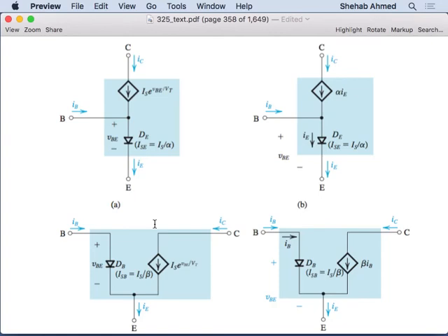The gain is different. You remember in the MOSFET, in the active region, what was the drain current controlled by? The overdrive voltage squared, in the saturation. Here, this is also relevant in the active region, because this is forward only in the active region, and I've created the other one reverse. That's why all the equations apply to what we're talking about, active and reverse, right? Active in the emitter base junction and reverse in the collector base junction here. So I've created current sources controlled by voltage.